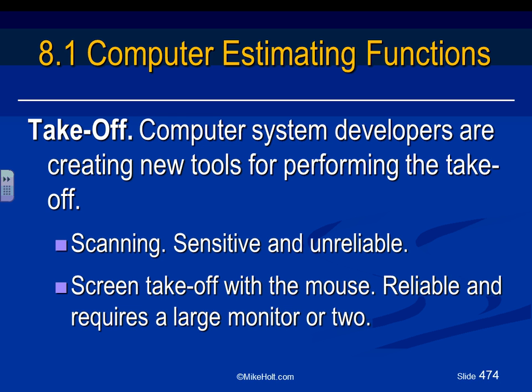One way of screen takeoff is interfacing the AutoCAD with the estimating software that you have, like Accubid or McCormick. What the guys do, all the blocks, that we call them blocks in AutoCAD, the block for receptacle will be identified in AutoCAD and at the same time in McCormick. McCormick is capable of doing that. I'm sure Accubid is the same thing. You can import the CAD into McCormick, identify the symbols so they can talk the same talk, and then the software will go, guys, suck all this information, count.